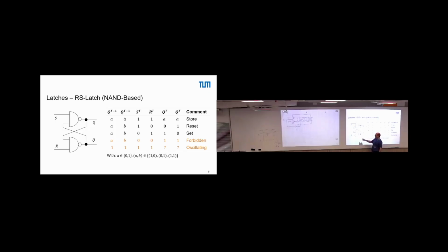If we switch off here at the wrong point in time, too early, the output here is not decided yet, right? So what does it have to do with this one here? If we toggle the clock too early, this RS latch did not settle. We are in something undecided, but we remove the input signal.